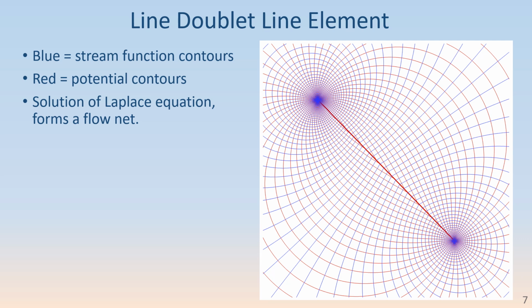And you can see at the tips there are vortices, and they tend to cancel each other out where these are strung together into a polyline of abutting segments. So it's still there, a little bit of a tiny vortex, but it only has a very local impact and doesn't really affect the flow pattern in the greater vicinity.